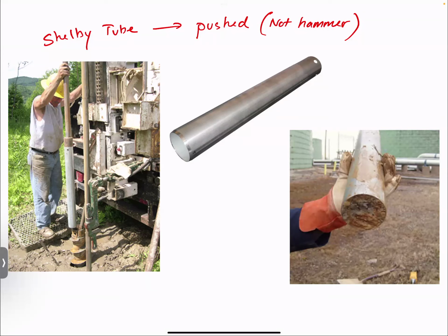So they drill the hole first, then put that in? Yeah. So you would drill down. This is used a lot for clay or fine grain soil. So you would drill to a depth where you are starting to get to clay or something, and then you would pull everything up and then put this in, slide it all the way down to the bottom, and then push it through using the ram of the truck or whatever.